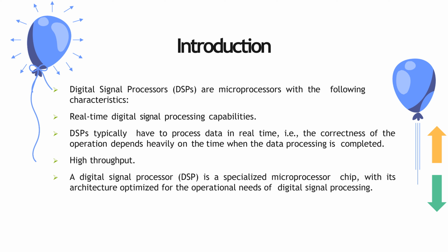The signal given to the DSP processor needs to be processed so that the information it contains can be displayed, analyzed, or converted into another type of signal that is to be used. For example, in an MP3 audio player, during the recording phase, the analog audio is input through a receiver or other source. This analog signal is converted into a digital signal using an analog to digital converter, and then it is passed through a DSP processor. The processor performs the MP3 encoding and saves the file into the memory.